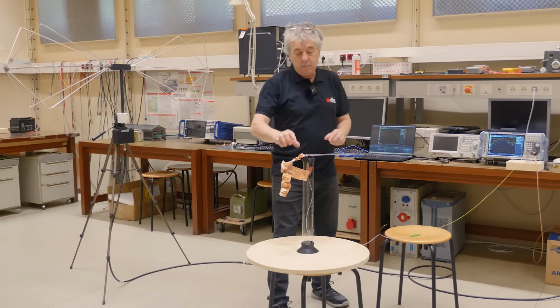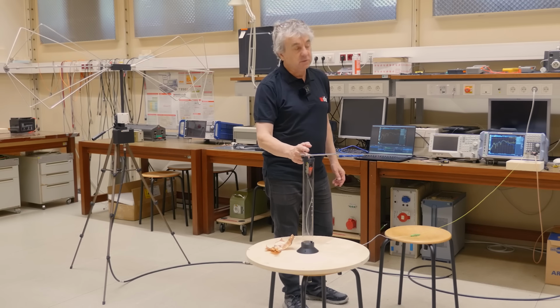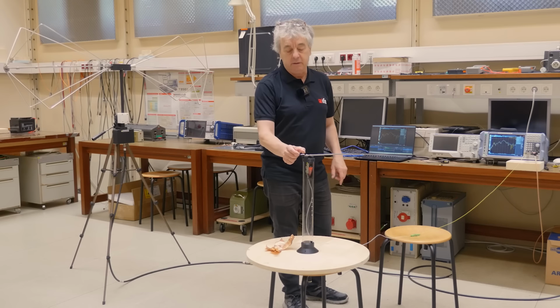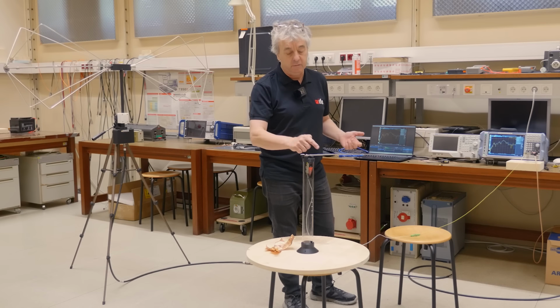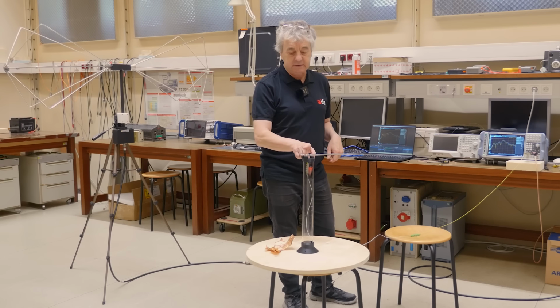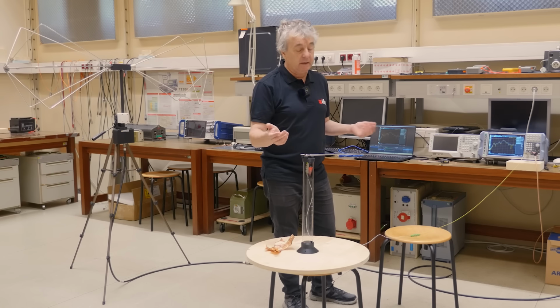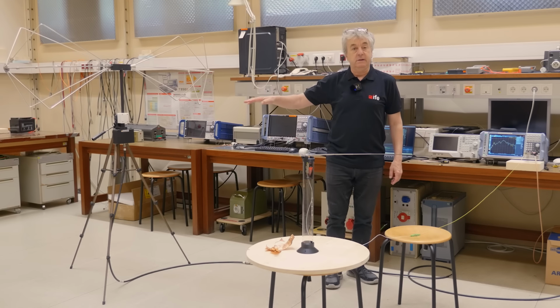Now, if we make the dipole very short on one side, the voltage source, which is in the middle, cannot drive current here because simply it's too short. There's not enough capacitance to ground or to the other side. So the current here is reduced, and the current here is, of course, the same as here, except opposite in phase, because current continuity is valid. If there's less current on the large element, we saw less field.